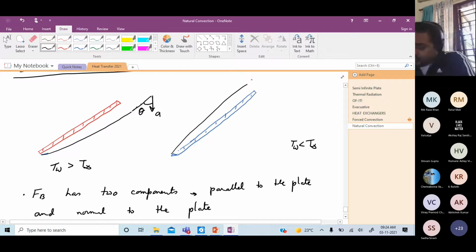However, from the top surface, as the fluid rises, its tendency is to go vertically up, isn't it? While the viscous forces are going to pull it back and let it cling to the surface, there will be a tendency to detach. So what happens is, there are packets of hot air that detach from the surface and leave.